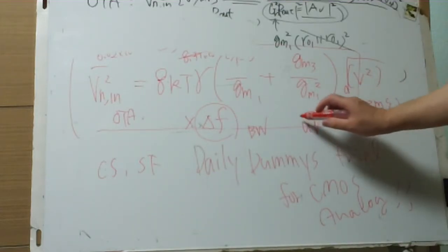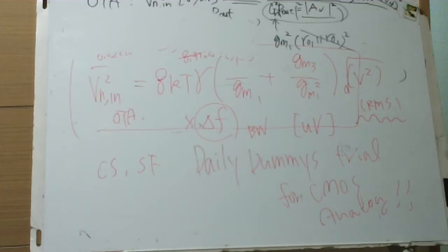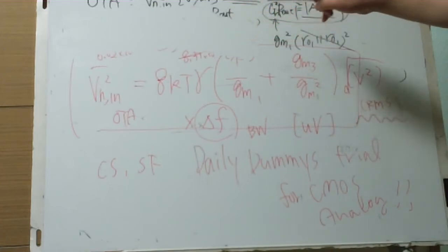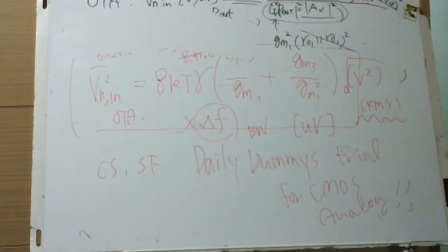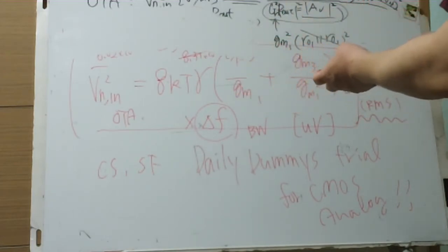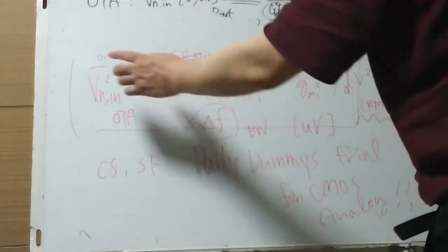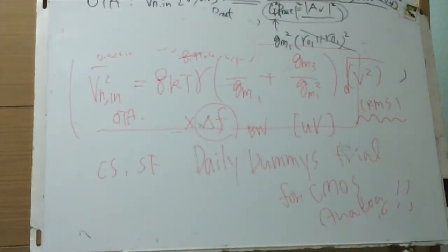namely in usual cases, several hundred microvolts of RMS value, which is actually observable using an oscilloscope. Some fluctuation, peak to peak values of several hundred microvolts. And the calculated output RMS value of several hundred microvolts is given by this noise voltage power times bandwidth, square root of all of it, we can get the RMS value. This is voltage.